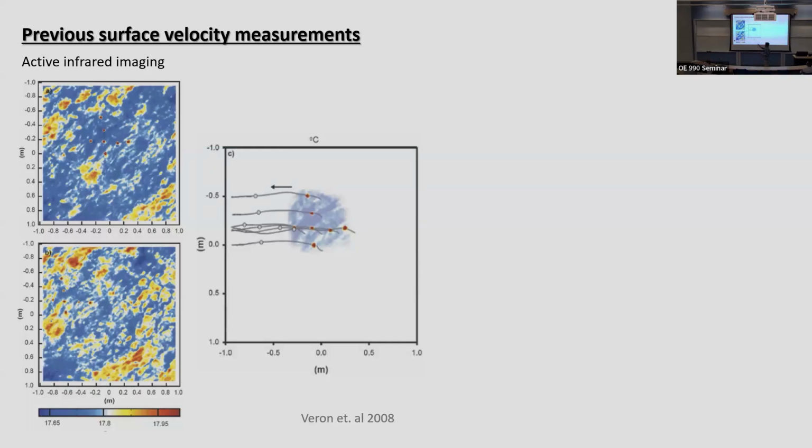The background features are just shown in this background color, but these are the spots which are marked, and that is at, say, time t1, and this image is at a different time, delta t. What's to see here is that these spots advected forward, and using this frame by frame advection of the spot, you could get your velocity measurement. These measurements are also Lagrangian in nature, so you follow the velocity field, you follow the particles. You could get a particle track right there, something like that.